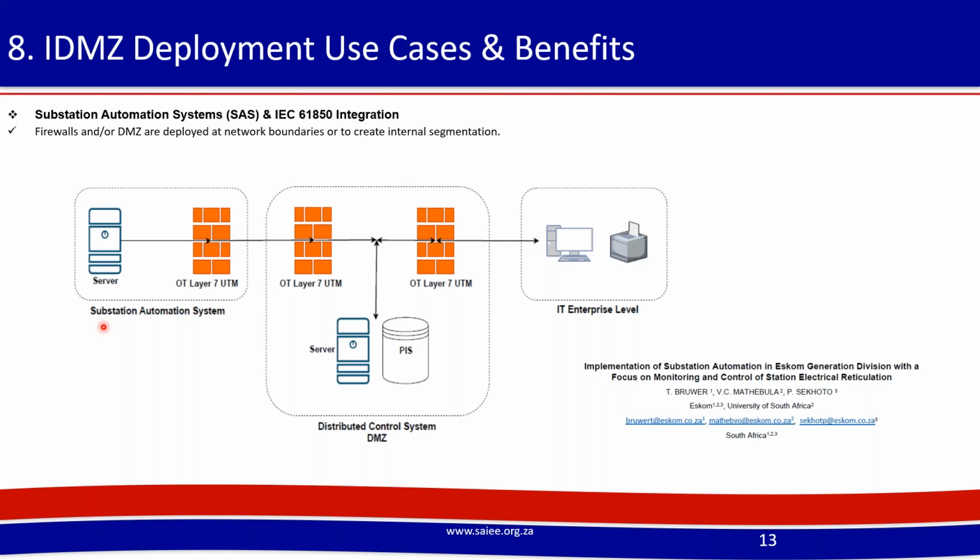They will have the big historian that can see the entire plant. But now if they need to interconnect with the electrical system, because the C&I people in charge of the DCS are not in control of this, this is the opportune time when you just put a firewall there, and then you can serve the data to your users who are primarily at the enterprise side.